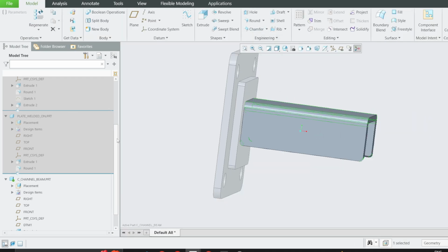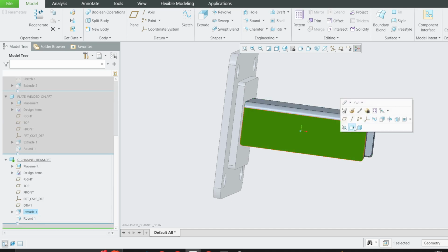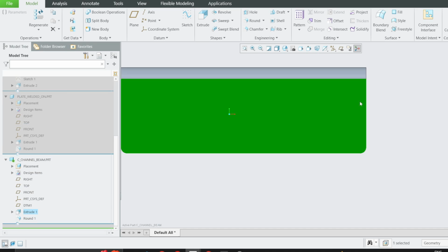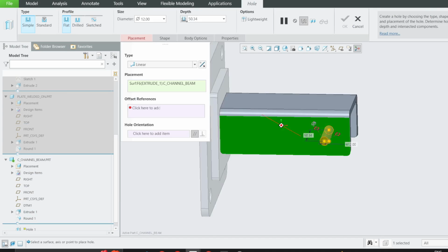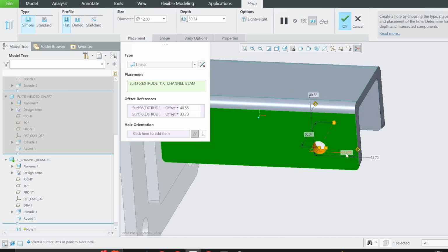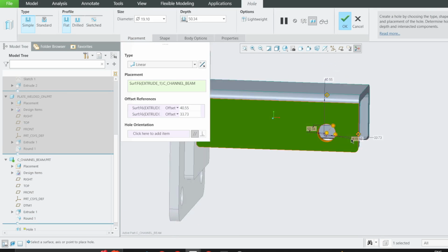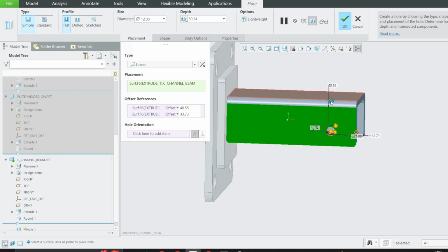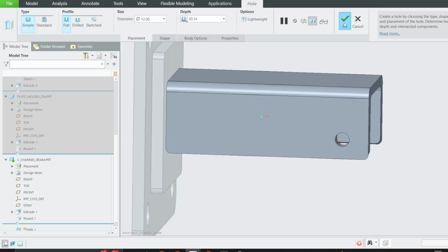Can go back to before. Let's now create a hole first here. Instead of extruding, you can use the hole command from this face to this face here. You can say create a hole of maybe 12. Let's go with the 12, maybe somewhere there, maybe somewhere there.